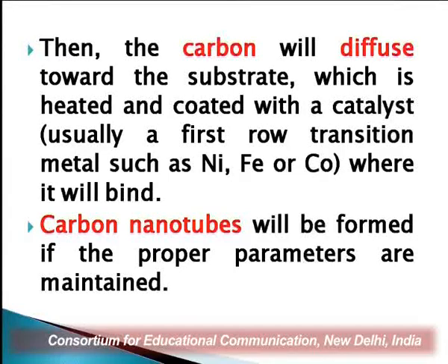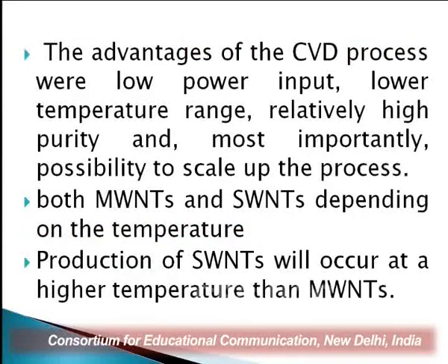Carbon nanotubes will be formed if the proper parameters are maintained. By using this method we can prepare both types of carbon nanotubes, multi-wall carbon nanotubes and single-wall carbon nanotubes, depending upon the temperature given to the tube. The production of single-wall carbon nanotubes will occur at a higher temperature than the multi-wall carbon nanotubes.